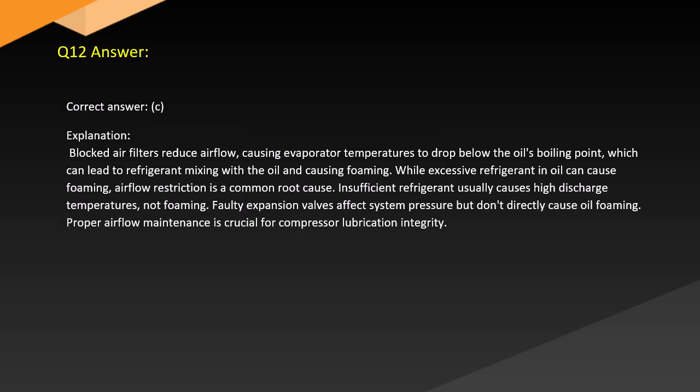Answer. Correct answer. C. Explanation. Blocked air filters reduce airflow, causing evaporator temperatures to drop below the oil's boiling point, which can lead to refrigerant mixing with the oil and causing foaming. While excessive refrigerant in oil can cause foaming, airflow restriction is a common root cause.